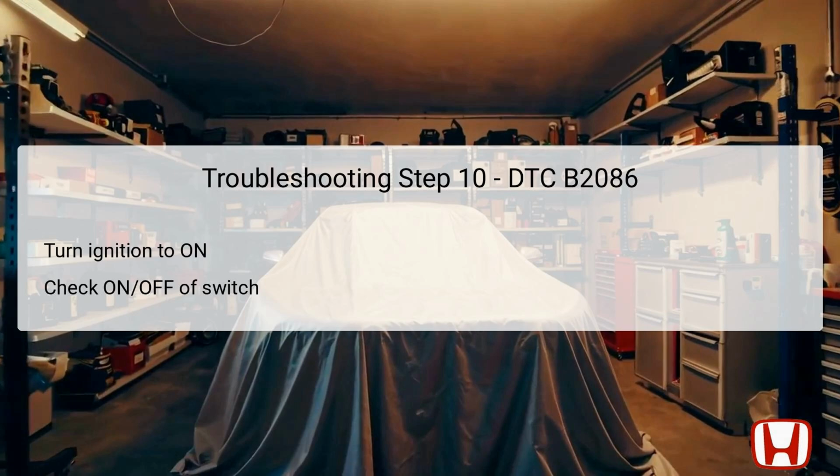If the information indicator remains off during this check, it signifies that the latch switch is faulty, and replacing the right power sliding door rear latch will be necessary. This step effectively verifies whether the previous component was the source of the error code. If the indication changes, it triggers the next step in the troubleshooting process. Performing this check can streamline the repair work significantly.